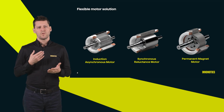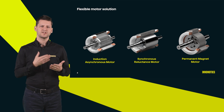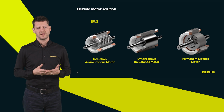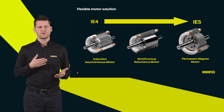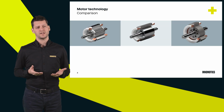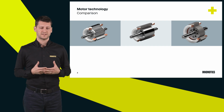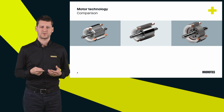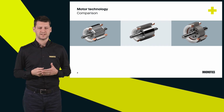One of the key differences between those technologies is that asynchronous motors are mainly in IE4 efficiency class, but the synchronous reluctance motors and permanent magnet motors are going to IE5 ultra efficiency class and even higher to IE6. Even the IE6 is not defined in standard yet. We are saying IE6 means it has 20% less losses compared to IE5 energy efficiency class.